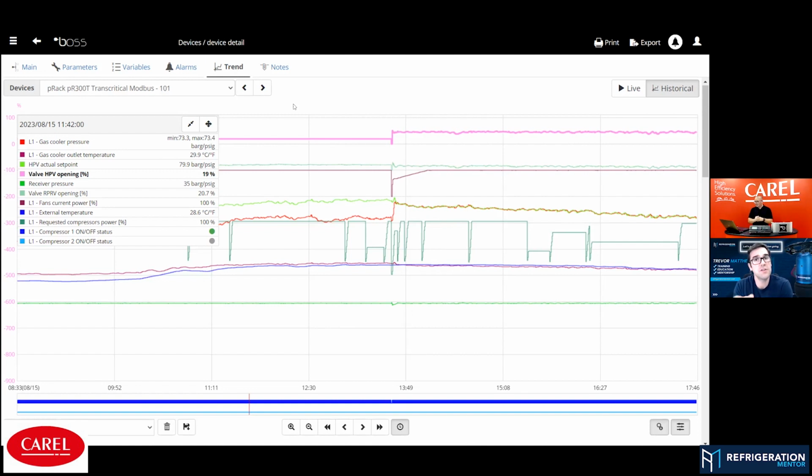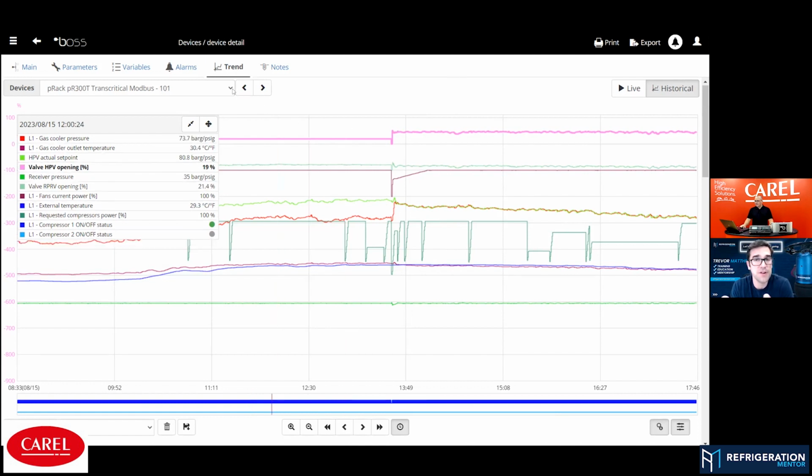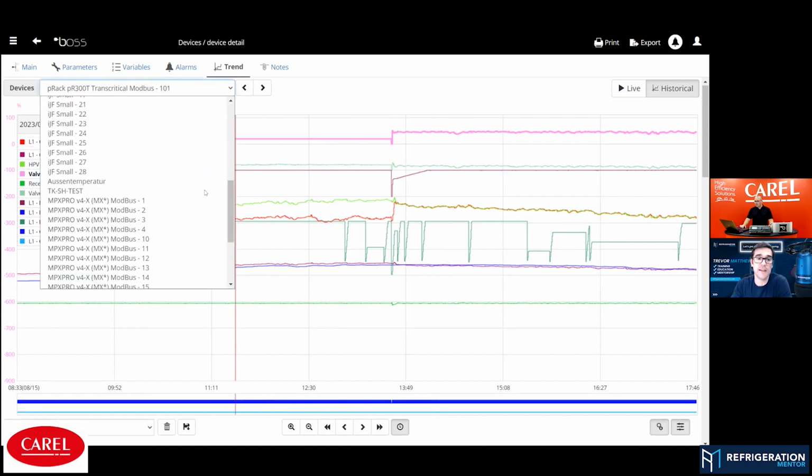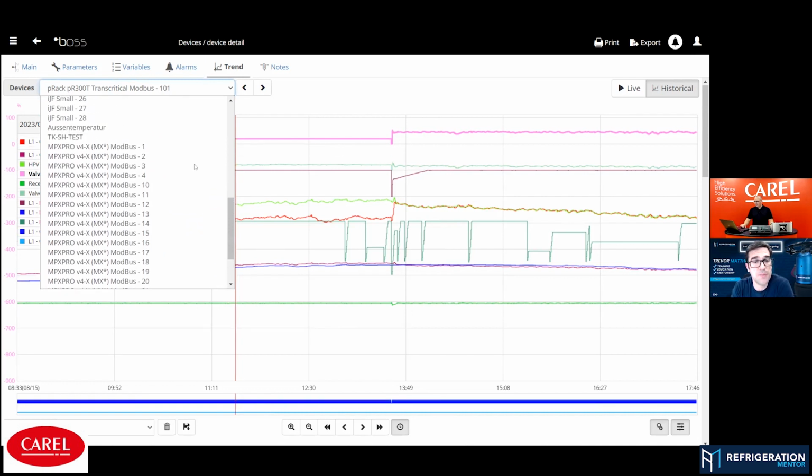Okay, so that's a good point, because in a lot of electronic valves, there's no exact feedback signal, so it doesn't tell you where you're to and from. So pulling that off, it was still adjusting, thinking it's moving at that point for, just say it's a minute or 30 seconds, whatever, and you put it back on. Now you're out of that, you're at a different position. So when it's put on, then now it's not regulating at that position it should be.